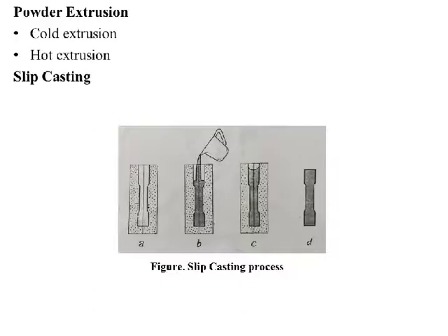Slip casting. In conventional powder metallurgy, we use pressure compacting of metal powders and subsequent sintering. That means both applying the pressure, compacting, and sintering of the compact take place in several steps. All these happen in one step in the case of slip casting.